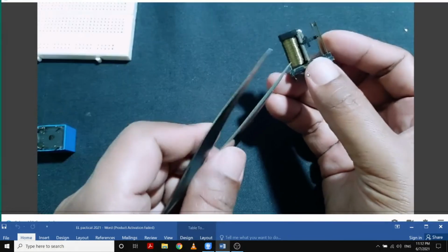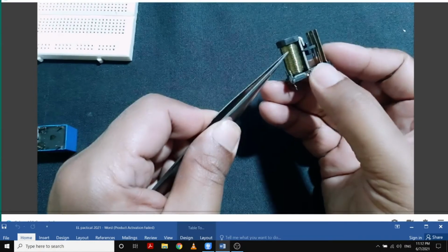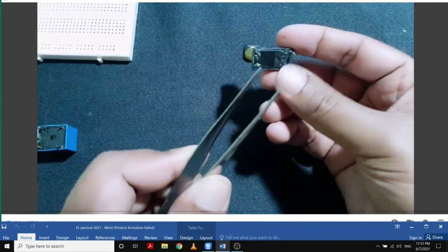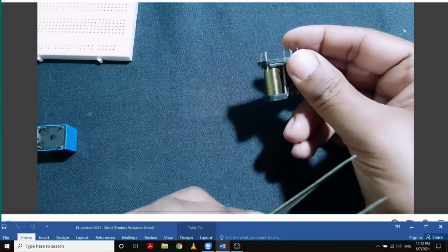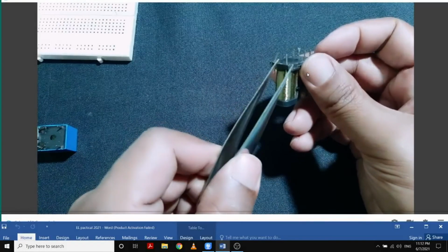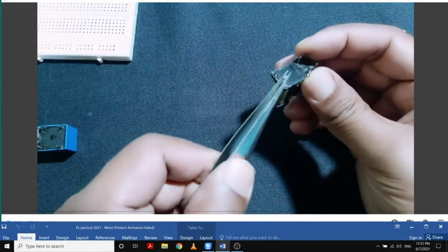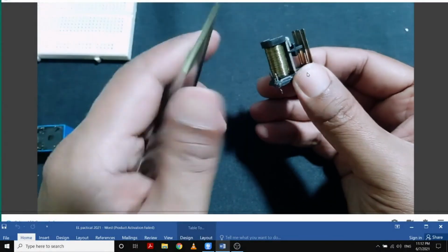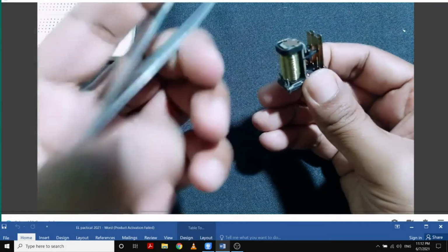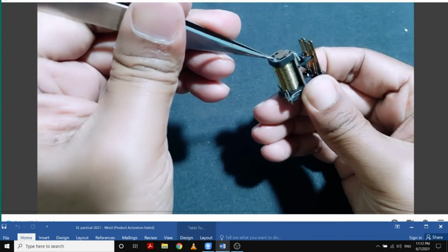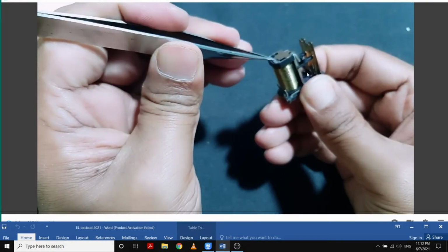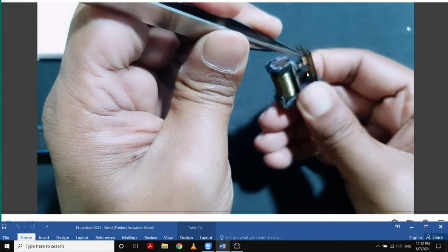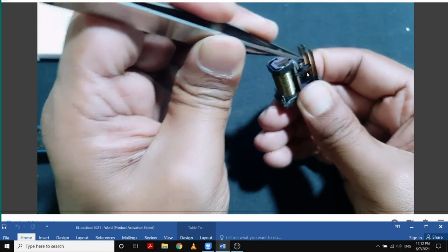So using this one, I can explain the function. So this is the electromagnet coil, and the coil connections are supplied to these two terminals. This is a different type of relay switch. The terminals in this switch are different from the one we previously saw. So here, when this gets electricity, there is a lever here. The lever pulls down, right? You can see this lever getting down. At the same time, this electrode is moving inside, right?